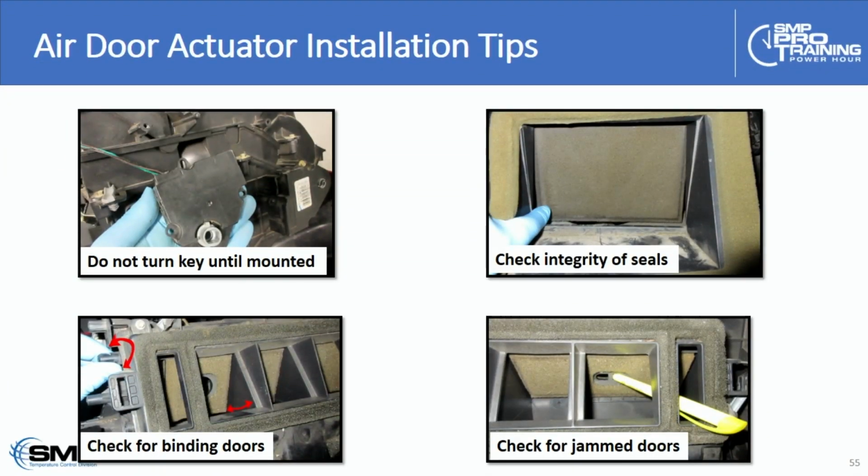Now, don't forget, never turn the key on until you have the actuator actually mounted on the case. Because if you turn the key on, the computer may try to recalibrate and move it through its full range of travel. If there's no resistance, the motor can often go off the end of its travel, and it will actually damage the motor inside.